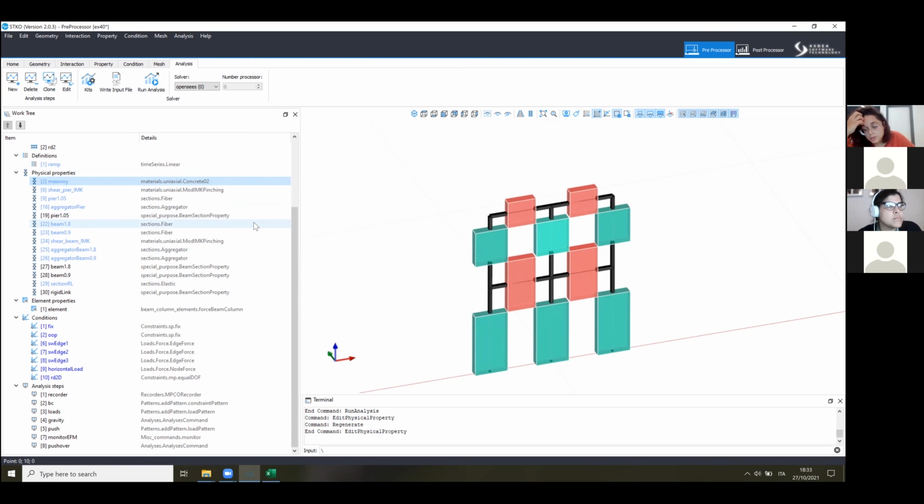If you're doing a distributed approach, your shear law has to be in terms of shear deformation. Instead, if you were doing a lumped approach, your shear law has to be in terms of shear drift. So you don't have a strain anymore, but you have a drift. And the same for your moment.